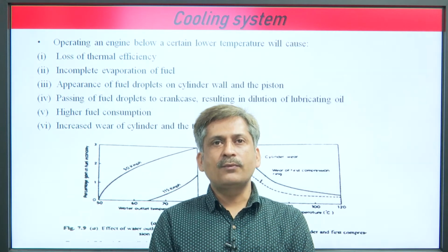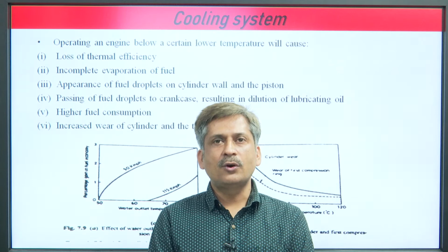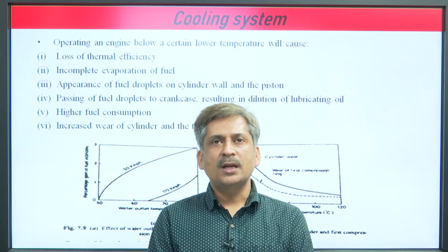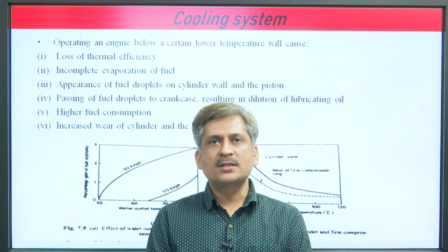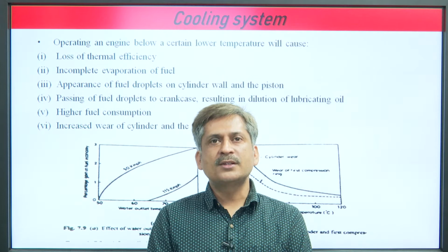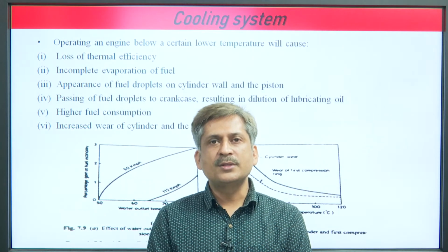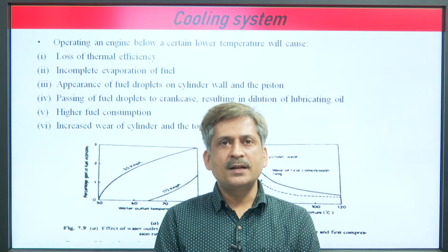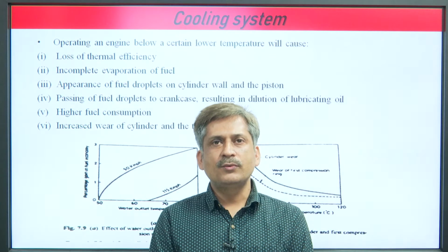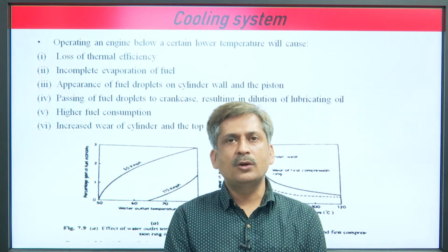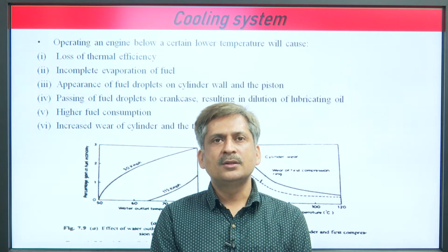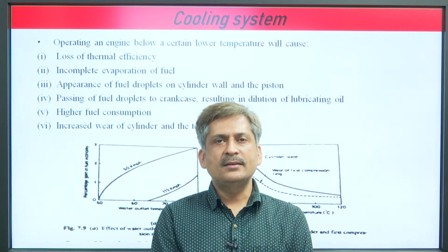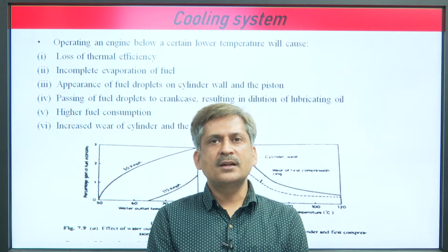Another effect is the appearance of fuel droplets on the cylinder wall and the piston. If the engine operates below a certain lower temperature, you will find fuel droplets on the cylinder wall and piston wall. These droplets are passed to the crankcase through the piston rings, and the result is dilution of the lubricating oil film.